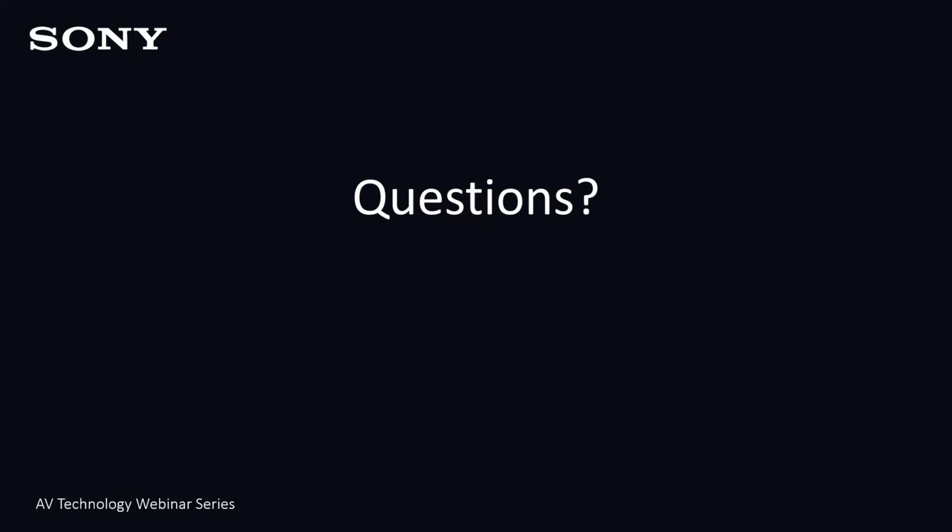Yeah, absolutely. So the PTZ auto tracking is going to do a mechanical pan, basically, as the person who you're tracking moves left and right. We're going to follow them with a camera. When they stop moving, we center them in the frame. But we're only doing pan. We're not doing any sort of mechanical tilt or mechanical zoom. So if they came towards the camera, they're going to get bigger in the frame. If they walk away from the camera, they'll get smaller in the frame.